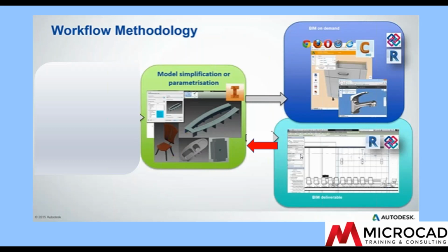So what we were showing in that last flow was that the architect designed a Sunscreen in Revit. It came to Inventor. We were able to use it for all the manufacturing and detailing. And if we'd wanted to, we could have sent that family back to Revit to update the architect. So it becomes a closed loop process, keeping everybody up to date with the design.